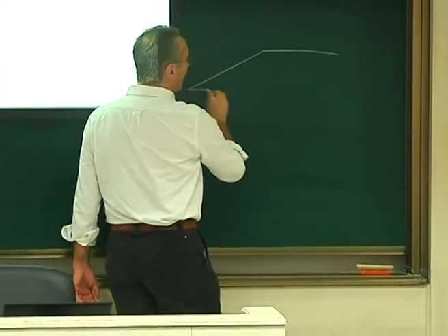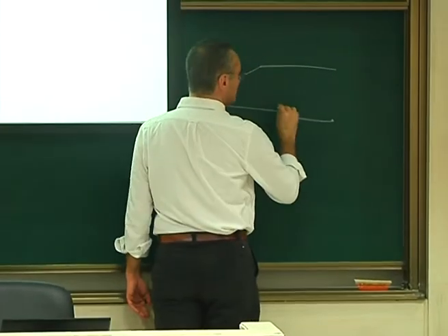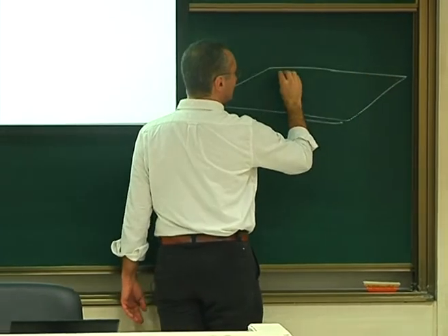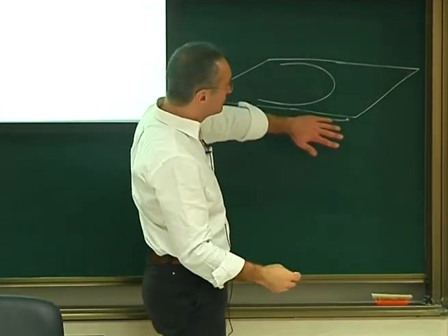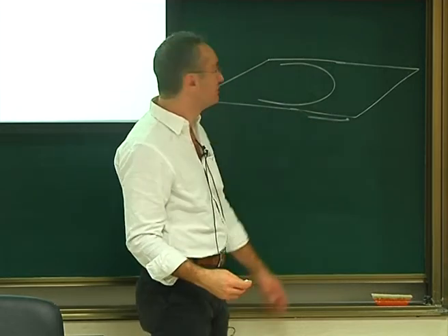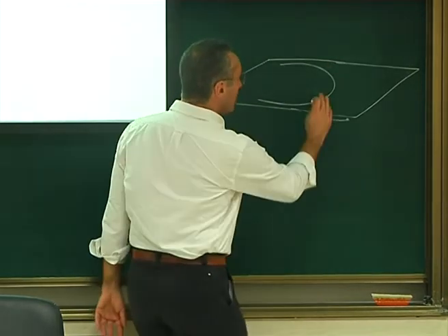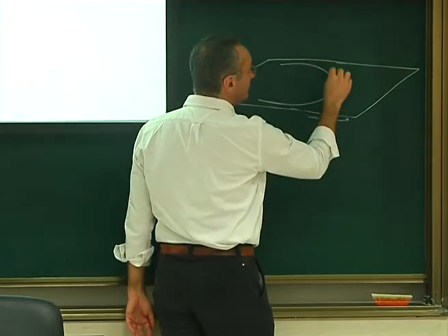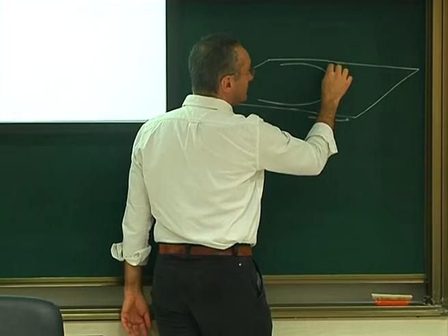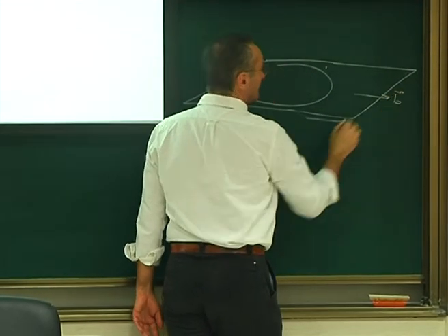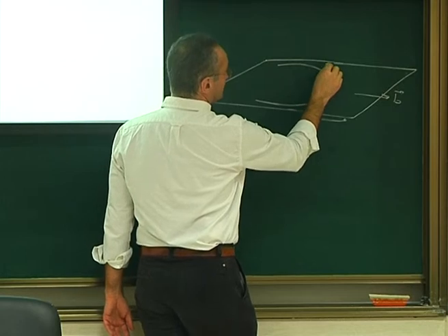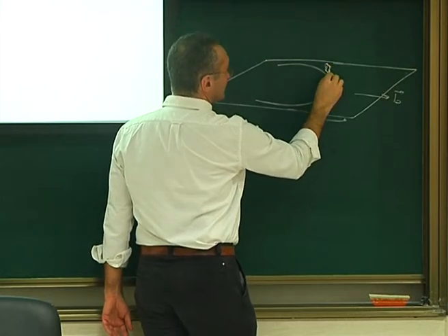if you assume that you have a highly mobile dislocation in a plane, like that, this is my dislocation in a plane, which is mobile very easily. So this is the interface between the persistent slip band and, let's say, the matrix. This is the PSB and this is the matrix. On top of the plane, if you put a small prismatic loop, for example, the prismatic loop will have to be, this is the Burgers vector, okay? It has to be something like that. That's a prismatic loop like this.